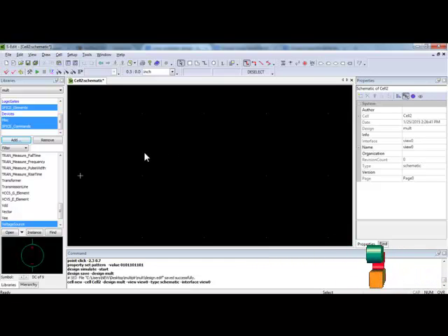After setting up the simulation, we have to load the library files. For the design of CMOS circuits, we need some CMOS components. Those CMOS components are contained in CMOS libraries. That means CMOS libraries contain the components which are required for CMOS design. Here you can see the components listed in the CMOS library. When you press add, it will lead you to a window. There you can locate the library file where you have stored it. From the location where you have stored it, you can select all the components which you need for your CMOS design.